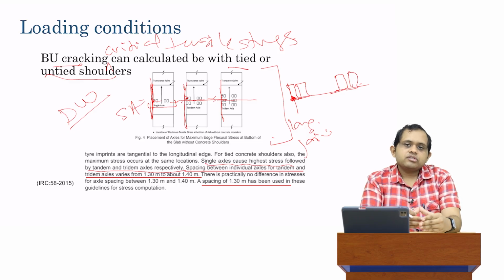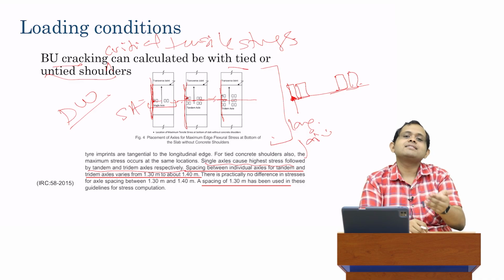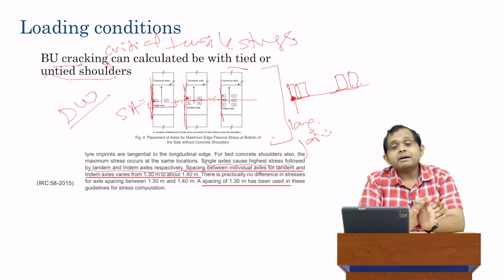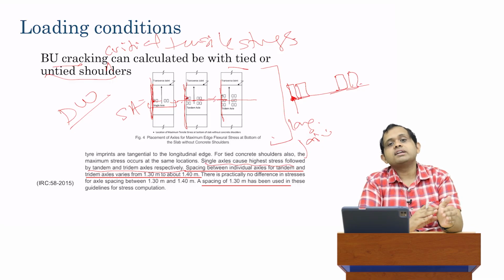But actually they're not proportionately heavier. Although tandem axles overall are heavier than single axles, they also have more tires, double the number of tires. So the load taken by each tire also decreases, and decreases disproportionately. In general, the load per tire is highest for single axles.